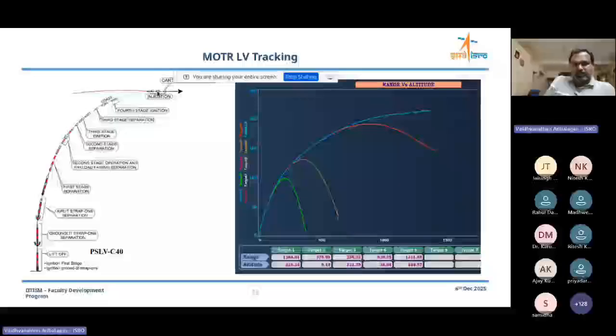So if you see, during the stage of say a launch vehicle, the launch vehicle also carries a transponder with it. So all the single object tracking radar gets locked to the launch vehicle using the transponder. Transponder is nothing but a beacon. Like if you send a signal, that launch vehicle will send back one more signal, so that you can track up to the range possible.